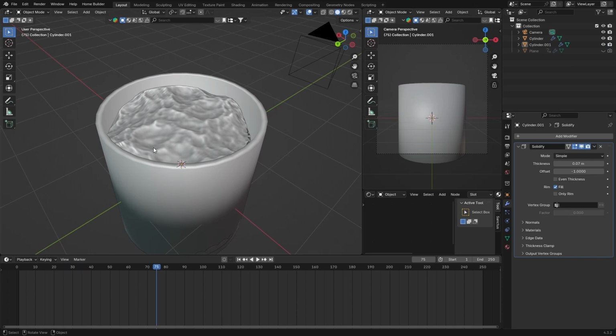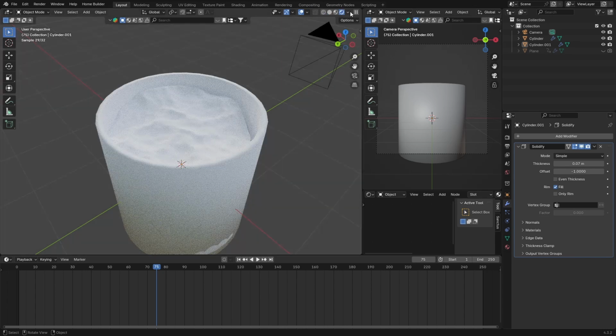So just make sure when you go G, like I said, I didn't do it properly, you need to select the axis. So hit G with your loop cut, G, and then the axis you want to scale it down so it scales down straight, otherwise it's going to make your object kind of skew. But you can see it's looking something like that.